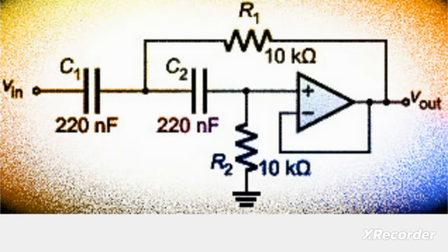So we clearly can observe the operational amplifier is biased or configured in such a way that its output is tied back to the negative pin of the amplifier, so that makes it configured as a voltage follower circuit, or in other words we say op-amp acts here as a buffer between input and the output pins of the amplifier.